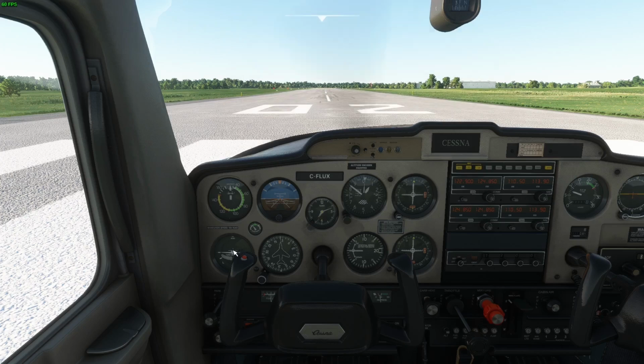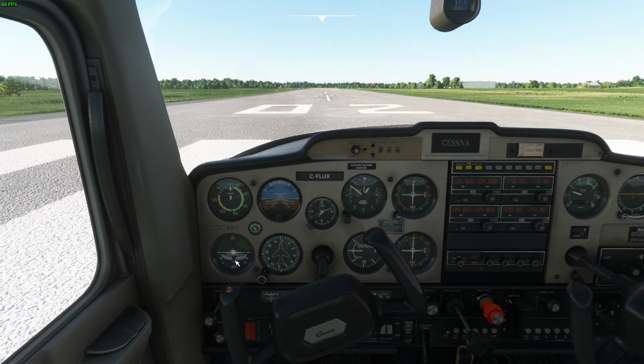And the turn and bank indicator, the little airplane. If you tip or bank the plane until the little plane lines up with a white line, that's a 20-degree bank. The ball tells you whether you're slipping inside the turn or skidding out away from the center of the turn. To correct it, use rudder. So if the ball slides to the left, you step on the left rudder. So that's correcting for a skid.